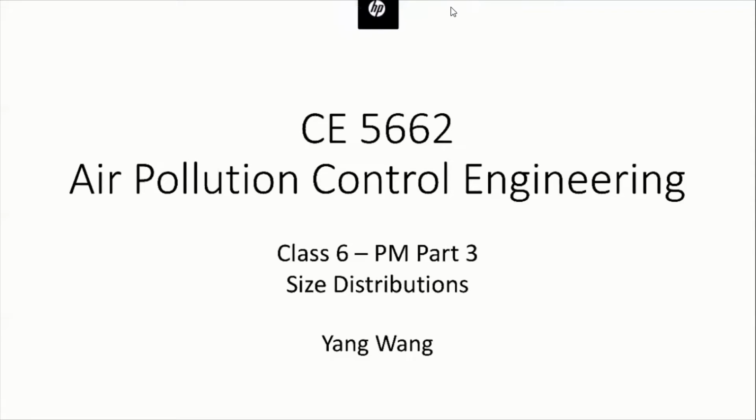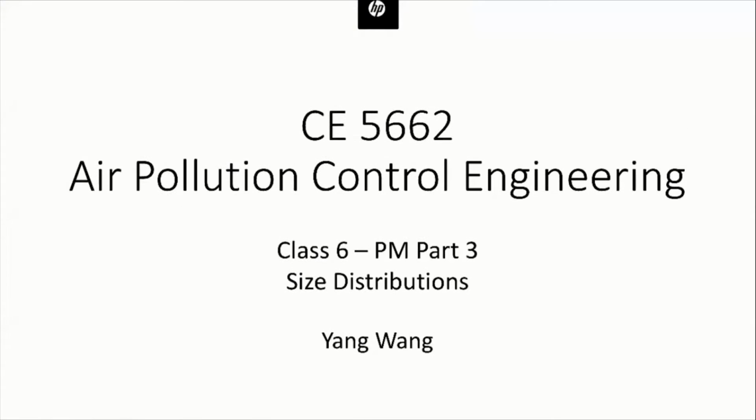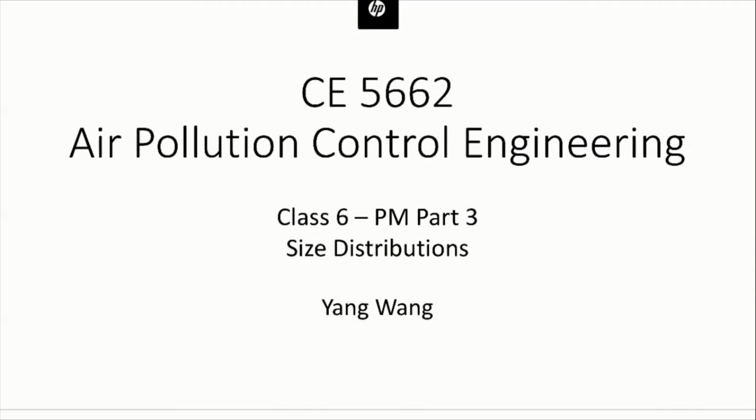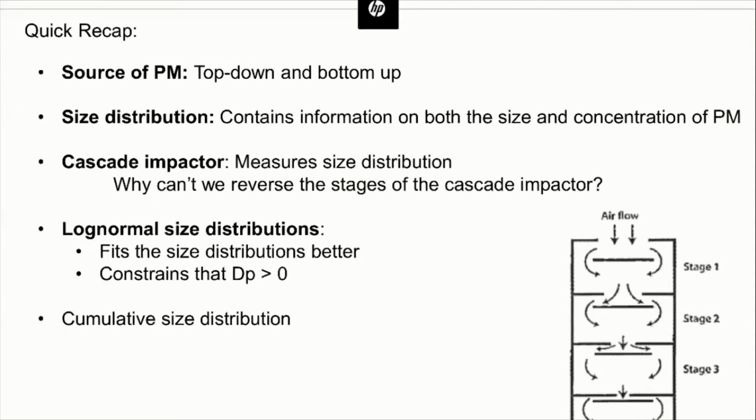So right now we're just getting some general information on the properties of particulate matter. We'll continue the discussion on size distributions. Last class we went through quite many equations on the size distributions, especially the log normal size distributions. So let's do a quick recap.